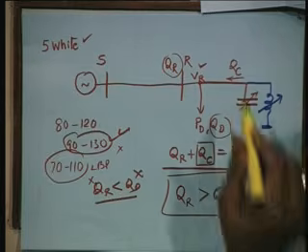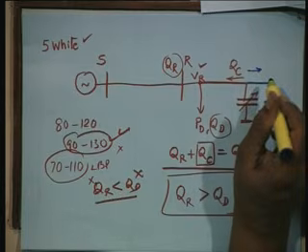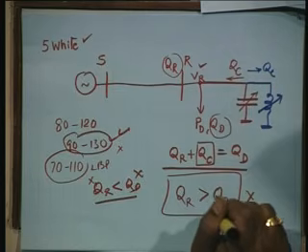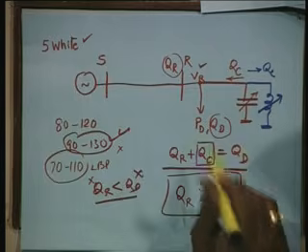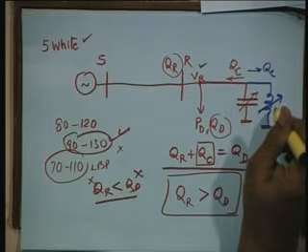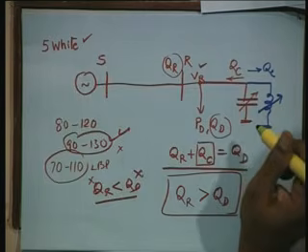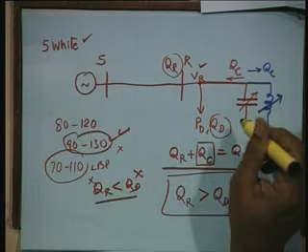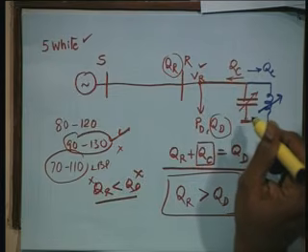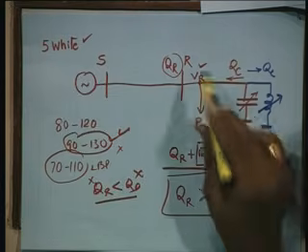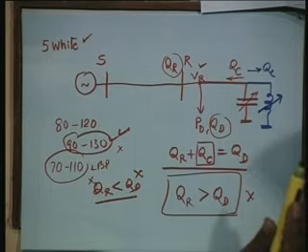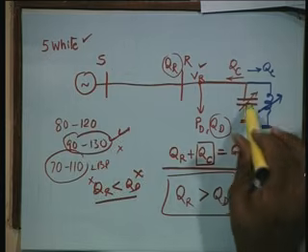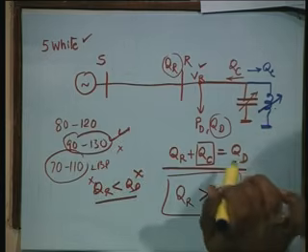Okay, and this will take some reactive power, absorb. So what is this extra will go here? Leading VARs, lagging VARs. Capacitors generate, inductors absorb, so that the voltage remains nice VR. This is called voltage control problem. And this is bank of capacitors and bank of inductors.